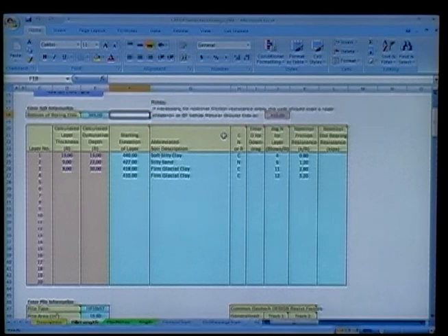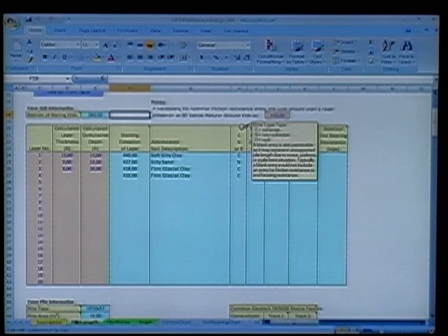All right, so you come in here, we're track 1, example 1. You enter your starting elevation of your layers, 440. You type this stuff in. This is calculated because it's red. So you put in your soft silty clay. It's a cohesive layer. You put in a C for that. It's described up a little there if you want to see that.